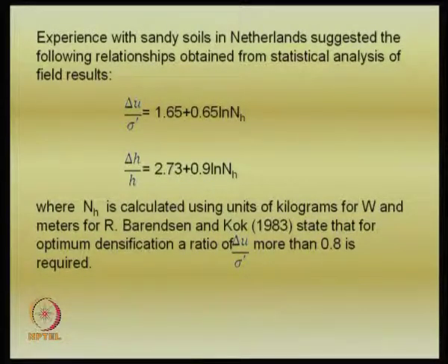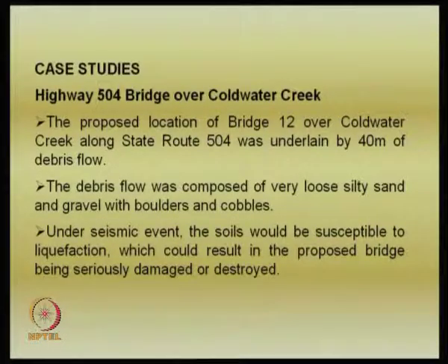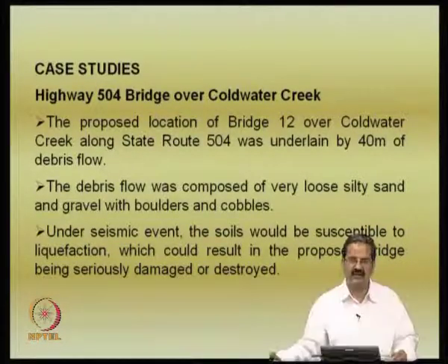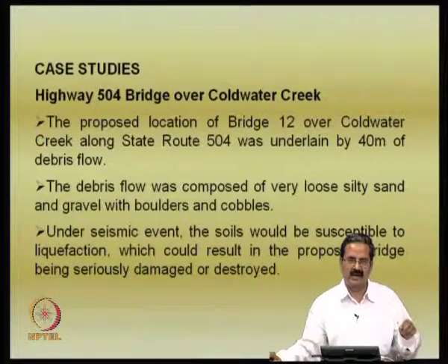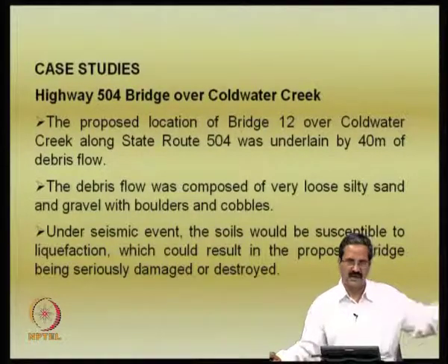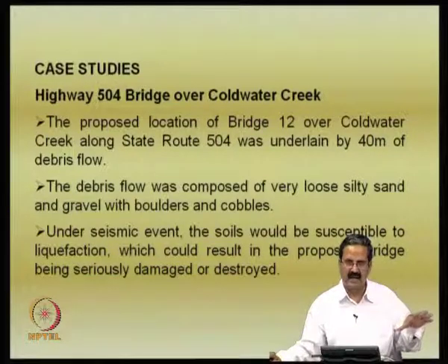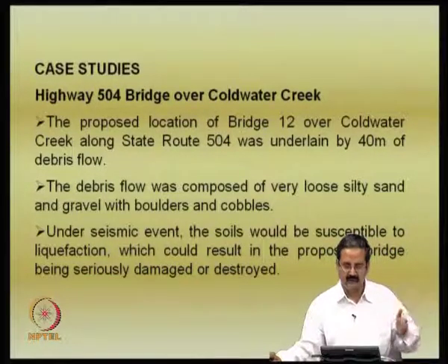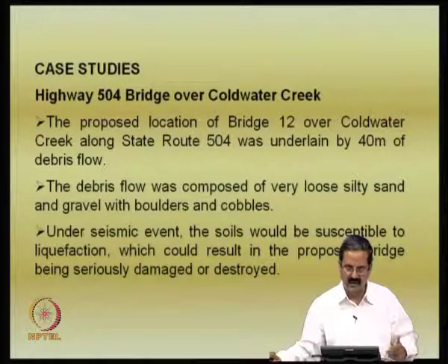guidelines. In fact, the best way would be to do a field case study, in which the first thing you should do is a trial test. Say I have done it using a charge of 1 ton or 500 kgs. What is the distance at which the area gets liquefied? You must be able to roughly calculate depending on the soil type, and then use that as a basis for refining your designs.